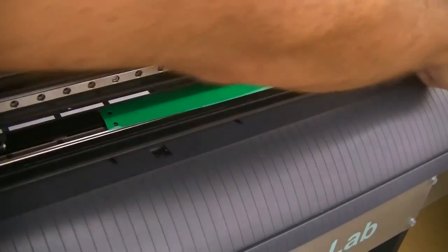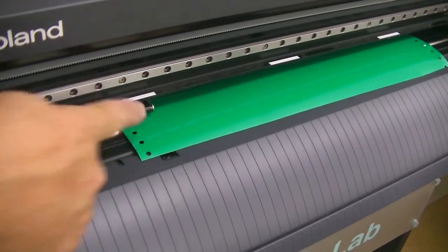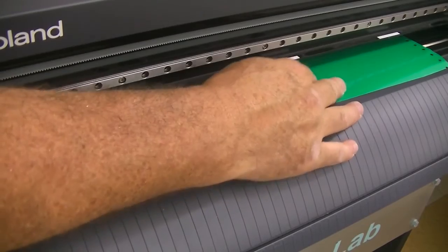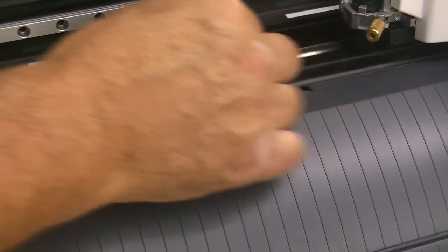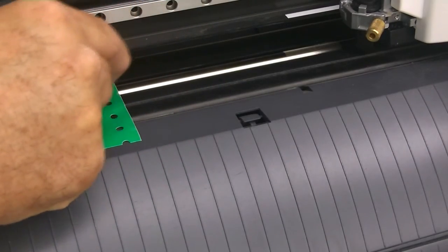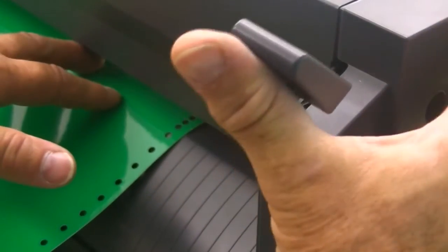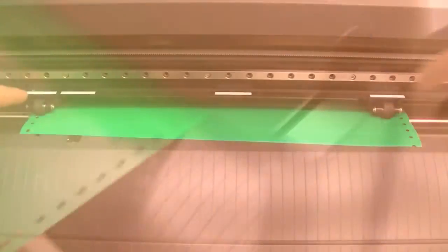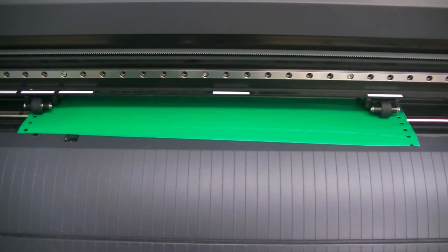Simply unlock the back lever again to release the wheels so they go up. Manually move the rollers over the white bars where the vinyl is. Do this to both sides. Push the locking handle back down, and the rollers will pinch the material into the machine. You can see both white bars right above both wheels holding the media.